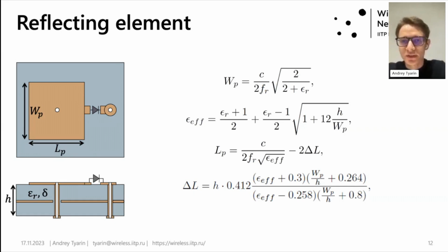Sometimes you see several patches connected to one tunable chip, but the rectangular patch is more universal in the sense of the functions that RIS can implement. Moreover, a rectangular patch is a good trade-off between bandwidth, phase shift range, and losses.